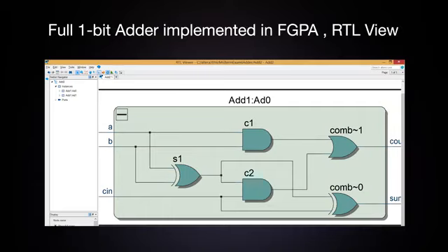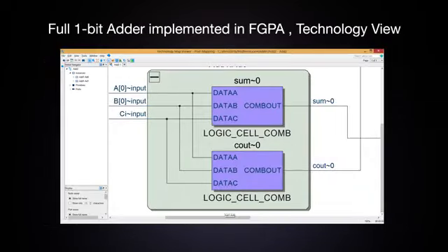RTL stands for Register Transfer Logic or Register Transfer Level. RTL is based on the concept that movement of data through digital logic can be viewed as logic diagrams with expressions representing the data variables that are stored in registers. It is generally a higher level representation than the gate level. So this is the result of an implementation of an adder in an Altera MAX 10 FPGA shown here using the Technology Map Viewer tool. It shows the implementation is made using 2 3-input LUTs.